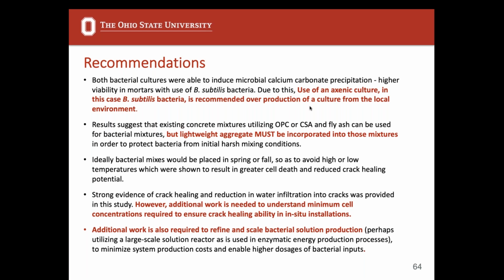So what we've discovered, because we actually tested an additional set of samples where we just had a bacteria within the curing solution, we thought maybe we can just apply a bacteria to the sample after it cracks when we need it, rather than incorporating the bacteria through all this work at the beginning. And we actually didn't see any healing in that sample that just had bacteria in the curing solution. So the curing solution is necessary when the crack happens.